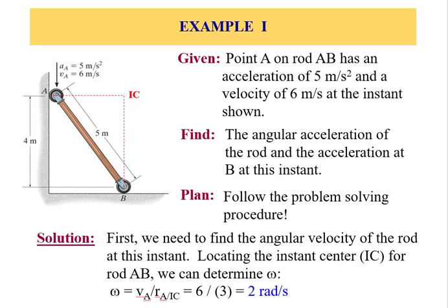So the method to solve follows the relative motion analysis, velocity and acceleration. Since the relative acceleration analysis does have an omega, the angular velocity of that rod, we need to calculate it. And to calculate the angular velocity of this rod, because it appears in that relative acceleration equation, we can use the instantaneous center of velocity, which is a graphical method, knowing the path of A is downward and B is to the right. We construct two orthogonal lines. One is orthogonal to VA, so this is the first line, and one is orthogonal to VB, which is this line, right? VB is to the right, the orthogonal.